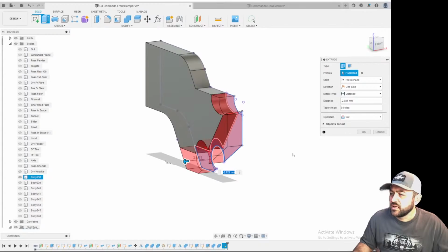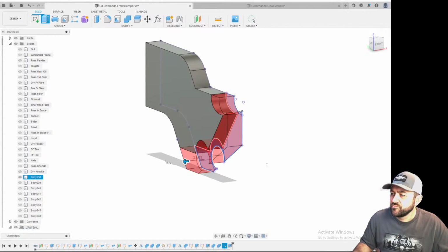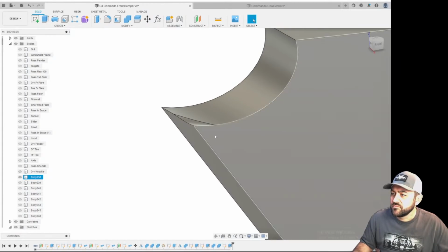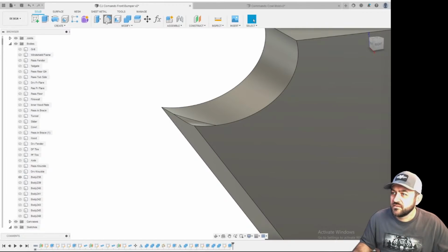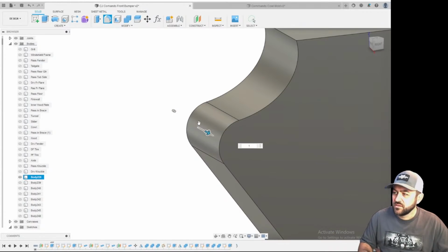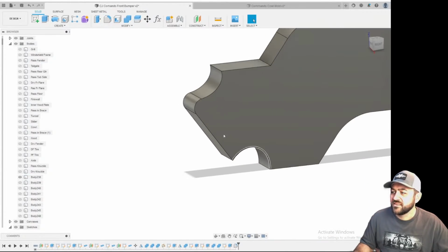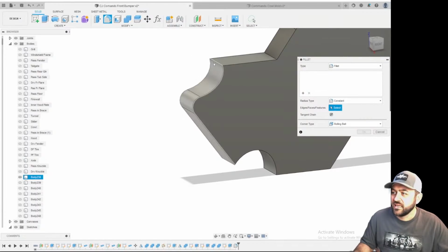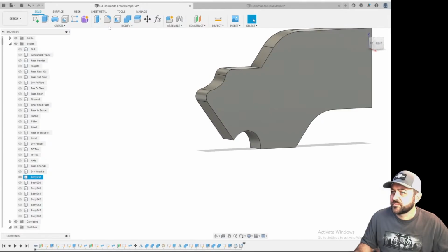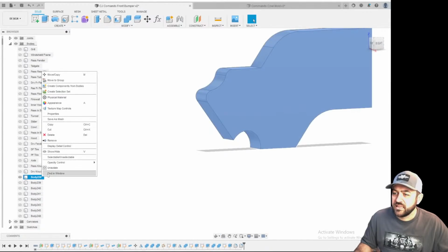And we're just going to cut it all the way through. And left a little hanger there. Let's see if I can just, yeah. Just throw a little 1 millimeter radius on some stuff, get it cleaned up. We'll unisolate this.